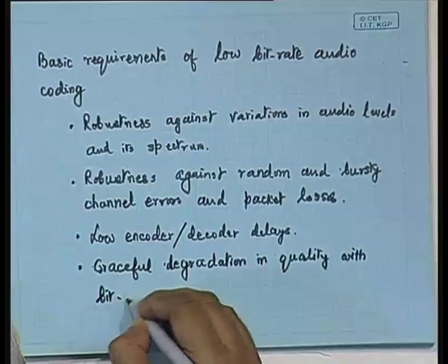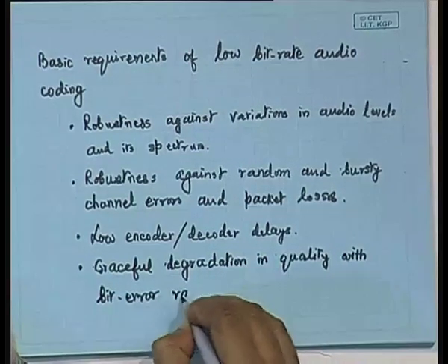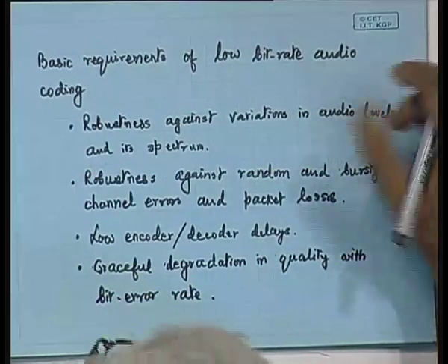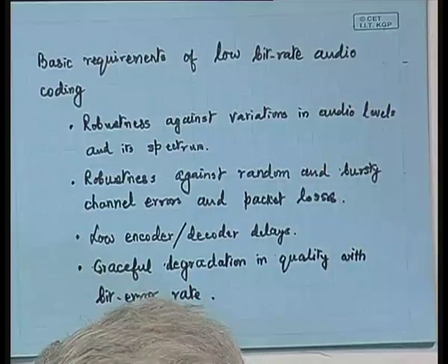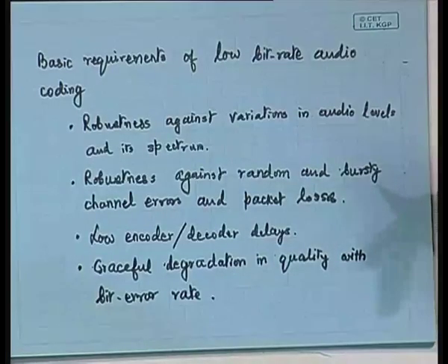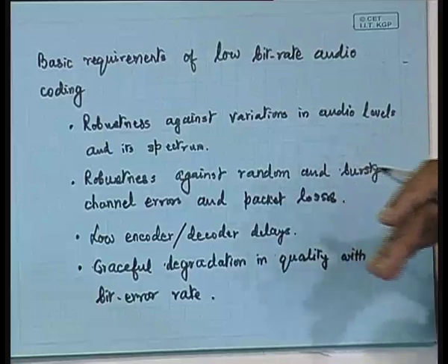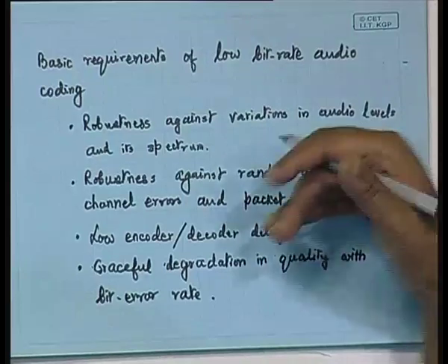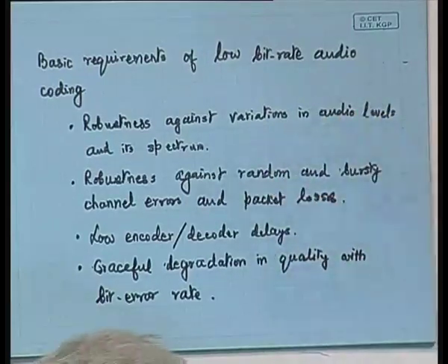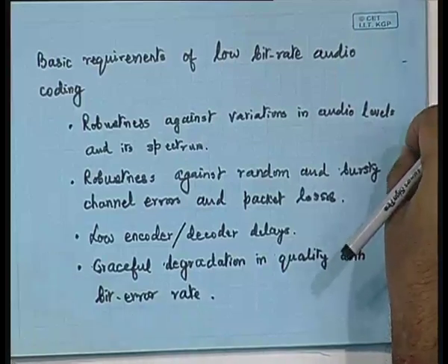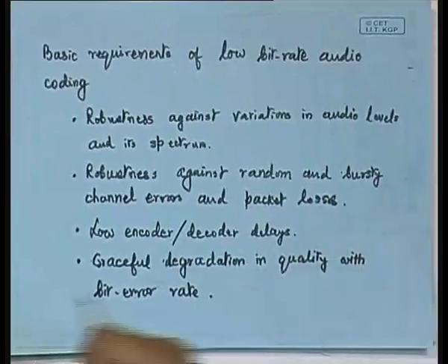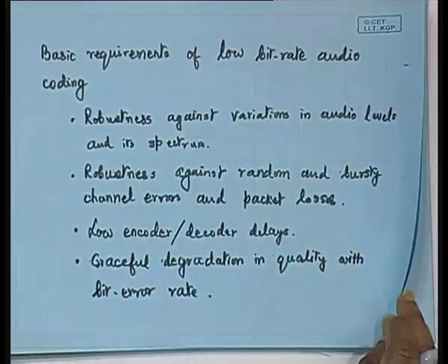So, that is why it is a good thing to study. When you design an audio coder, the good thing should be to study its quality as the bit error rate is varied. Okay. It should have a smooth variation and a graceful degradation, not that up to certain bit error rate it works fine and beyond certain bit error rate it never works.